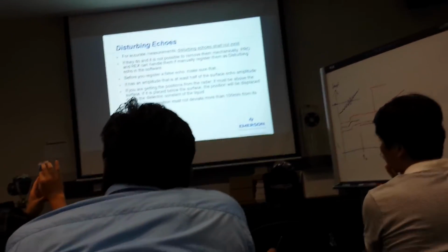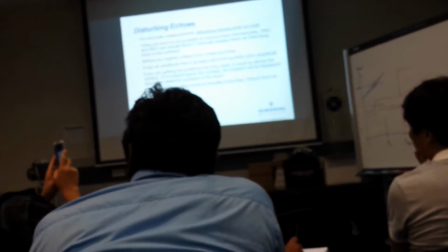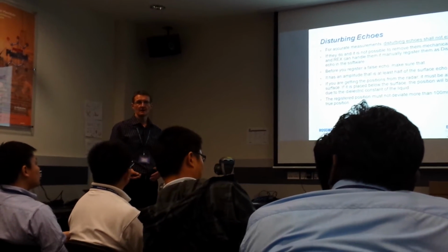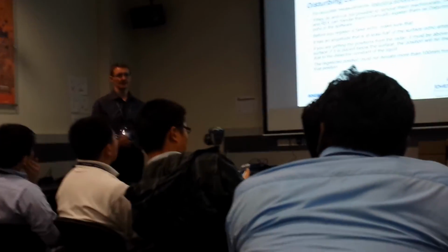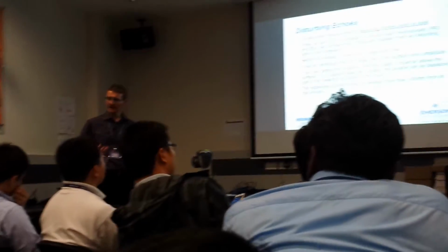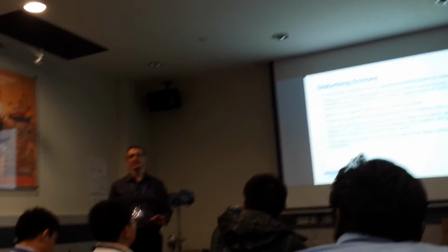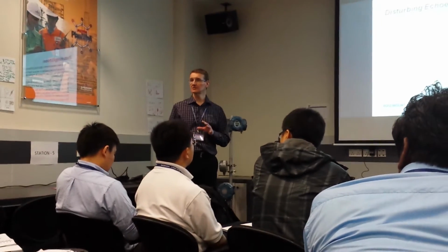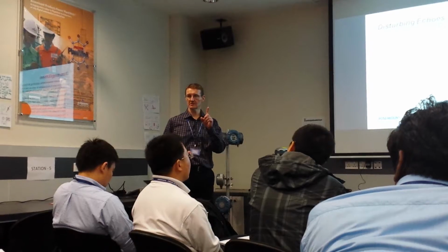A reason for having a disturbing object could be that when we installed the radar, that was the only place we could put the radar: just one existing manhole. They don't want to weld, and they don't want to remove any objects, anything like that. So we say, okay, fine. We can put the radar, we can measure, there will not be any problems, but the accuracy will be less because of this fixed object which will give us a disturbance. So we have to point out those things.